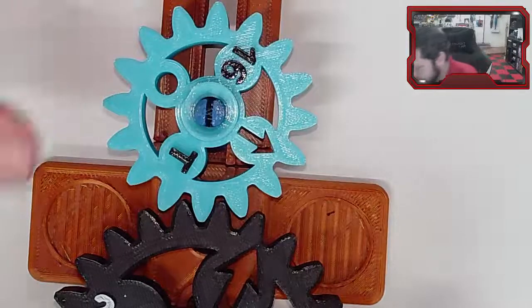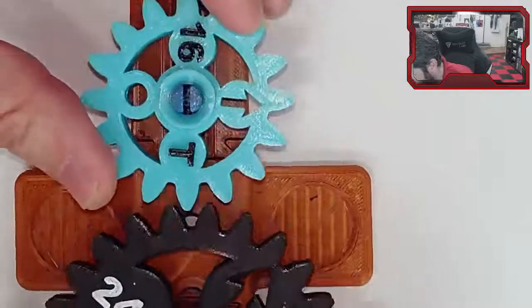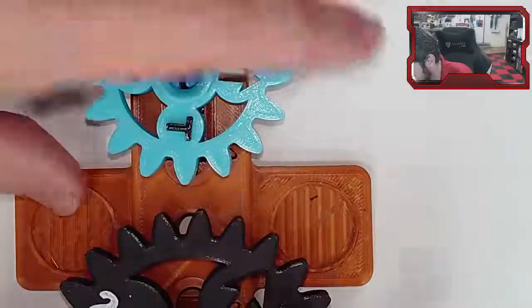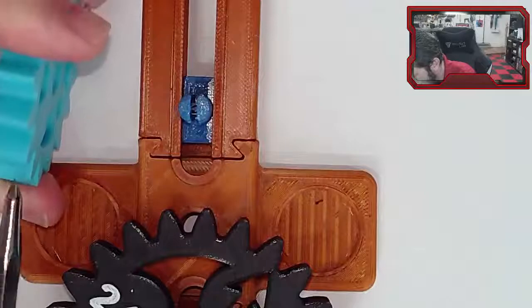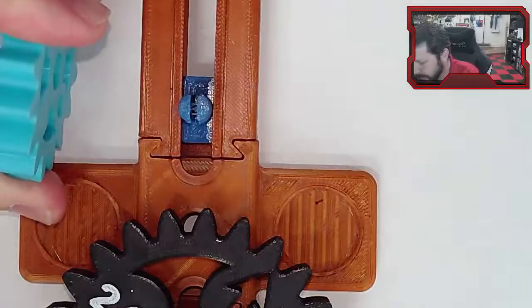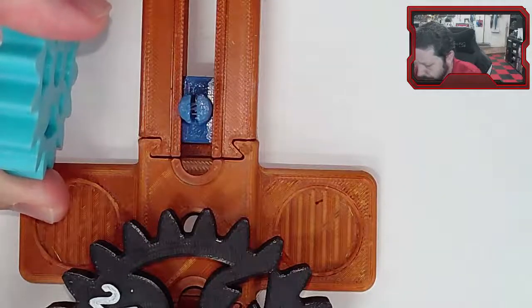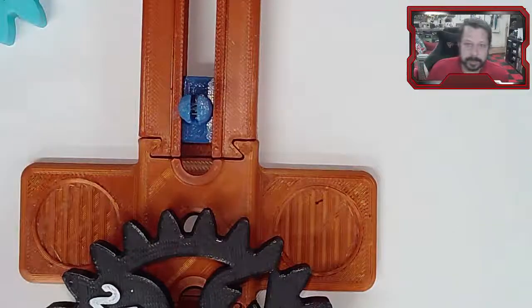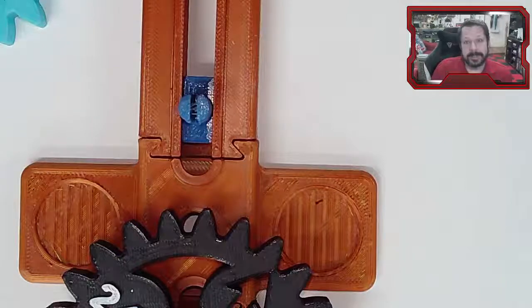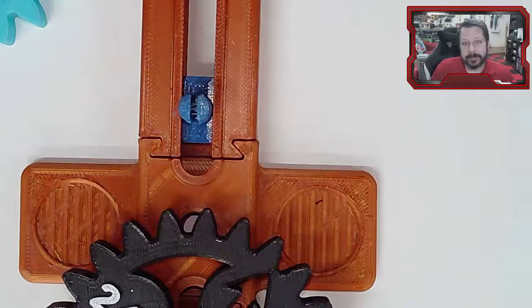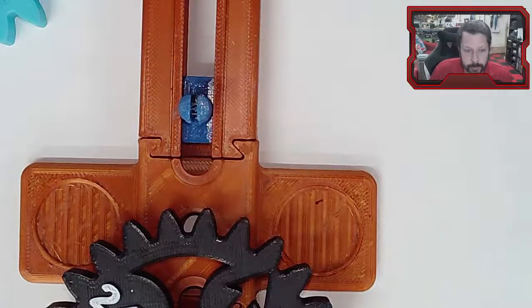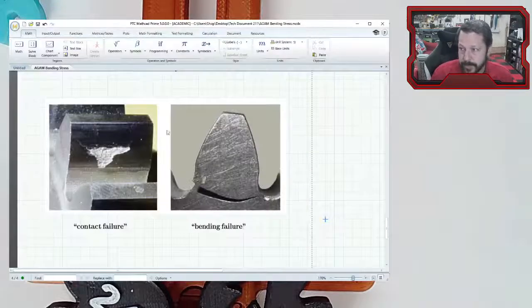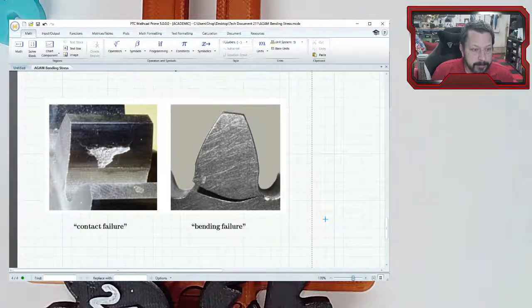Since that in these gear teeth occurs in a contact line across the face of a tooth, there'll be some line where that change from one direction to the other occurs. That line ends up repeatedly getting that area of no lubricant support. And so what you end up with is a line of pits across here.